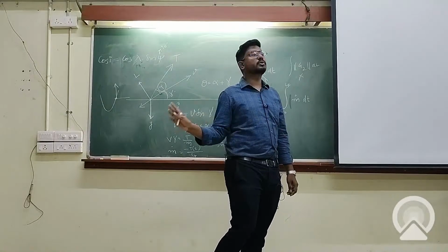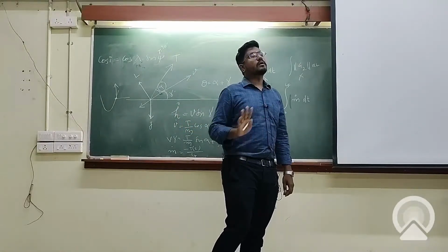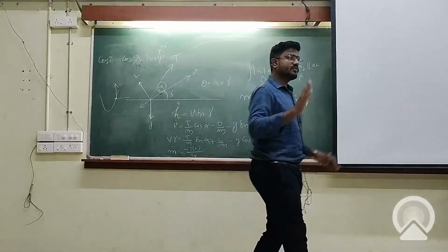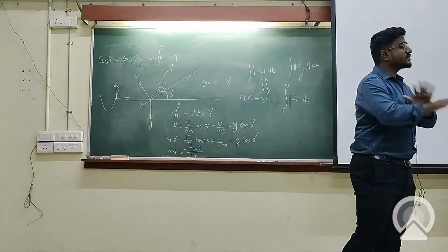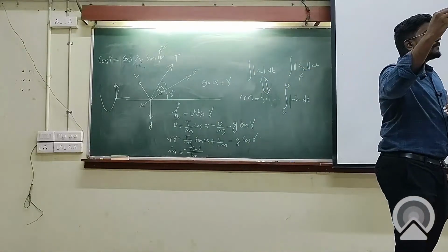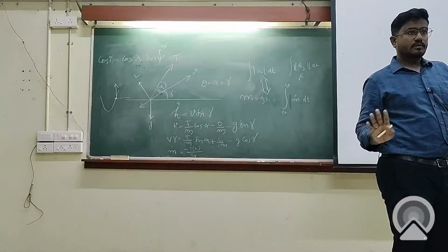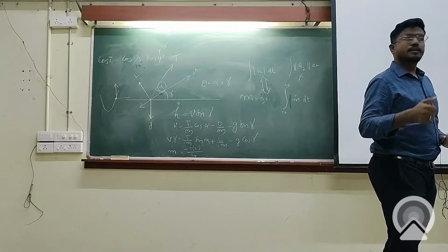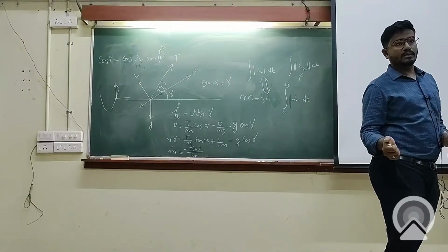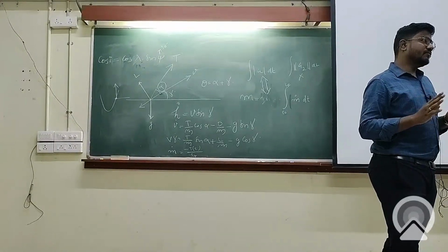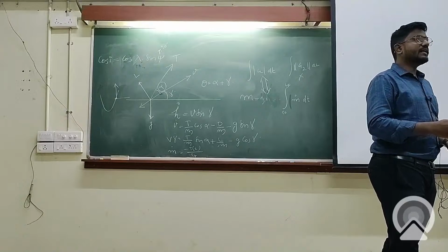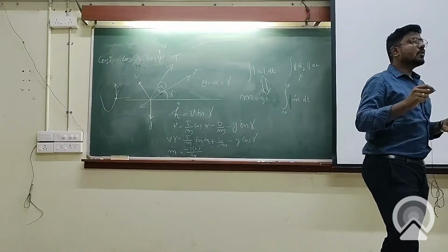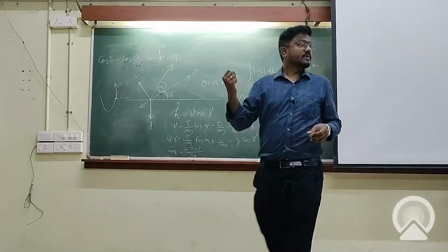What we do is we steer for the initial few seconds, up until a point where the dynamic pressure is not significant. Once the dynamic pressure is significant, steering is not a priority. So whatever steering we are doing, we have to finish it before that. Okay. So that is the kick rate.